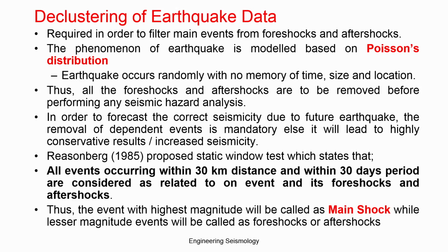That means there should not be any overlap of the same earthquake in the region. That has to be taken care of. All the foreshocks and aftershocks have to be removed before performing any seismic hazard analysis. Before doing seismic hazard analysis, you need to remove the foreshocks and aftershocks.